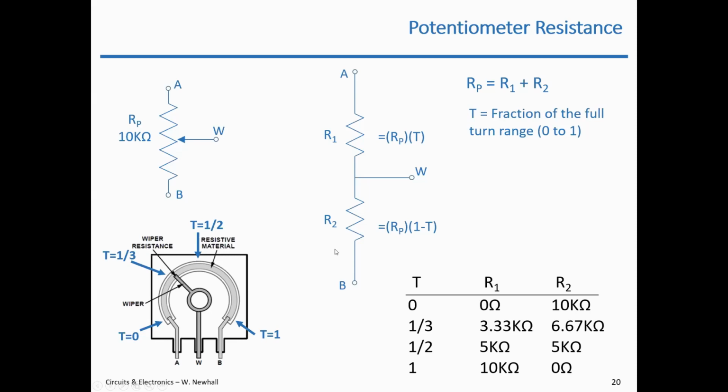Its resistance from A to B doesn't change, but its resistance between A and W, and B and W, changes. If you connect a wire between B and W, then between A and B, you'll see in a problem that R1 controls the resistance between A and B. Let me show you a practical application of this and really why you need the 3 terminals.